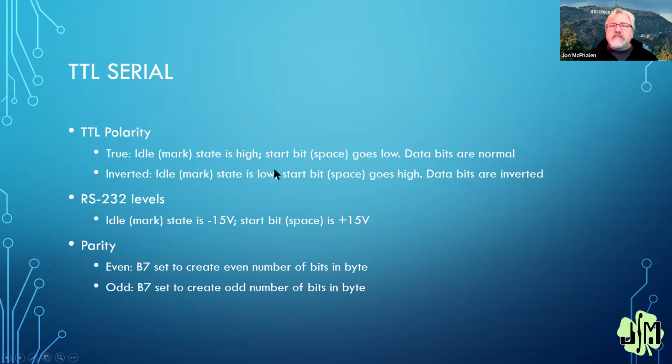Now, there are devices that work this way that we have to deal with. And the great thing about the Propeller is that if you have a device that wants to run inverted mode, like I think the servos that we did for the RC transmitter, it used an inverted mode. With the Propeller in the pin configuration, we can toss an inverter into the pin without having to hook up any external circuitry. It's a really fantastic feature. We can write our code per normal and then just say, oh, invert that pin, and everything else gets sorted out. It's really, really great.